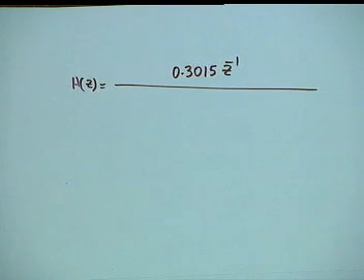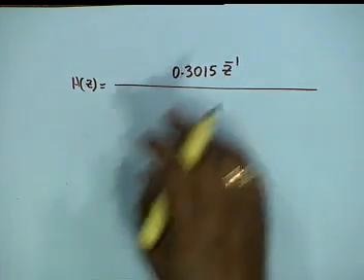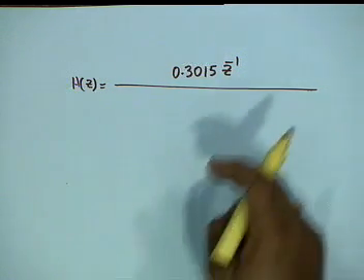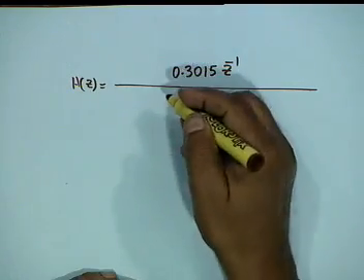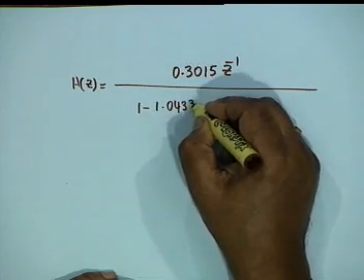In the Butterworth filter, in the Butterworth design, we had in the numerator 1 plus z inverse. You see the difference. So at omega equal to pi, Butterworth was guaranteed to give a 0, Butterworth low pass filter. There is no guarantee here. It will be a small quantity, but not 0 because of aliasing. Okay? Aliasing shows its teeth like this, and the denominator is 1 minus 1.0433.